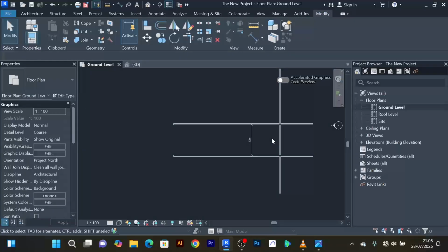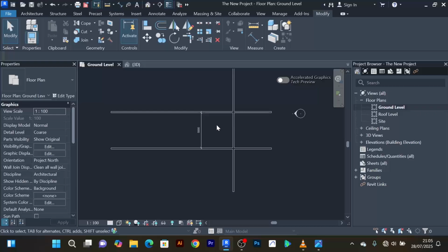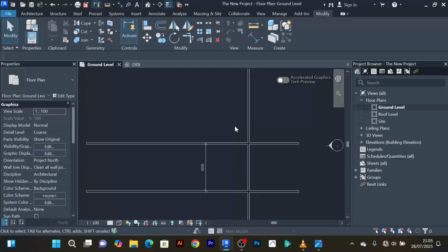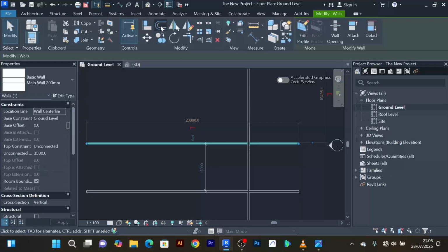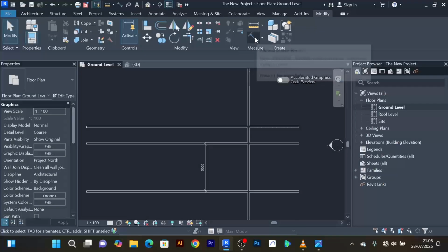So simply like that, we have created that option. Now I can do the same. I can keep offsetting until I get what I want. Now from here I am going to offset. Let me offset, let's just say 1.8, and I'll offset from here. I'll escape and escape. I'll come to the align dimension.